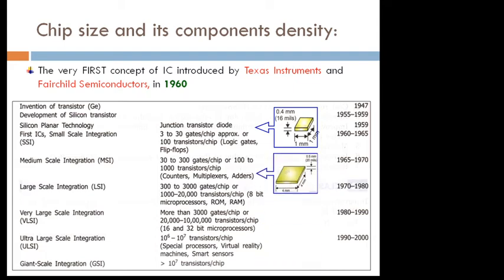अगर मैं मीडियम स्केल की बात करूं तो मीडियम स्केल इंटीग्रेशन then it would be some around 4 mm by 4 mm. So just again look at your scale, just 4 black marks from your centimeter marking, so even lesser than half centimeter by lesser than half centimeter, and again thickness is hardly 0.5 mm. And the last one is the large scale integration, just 10 mm माने 1 centimeter by 1 centimeter, and again thickness is hardly 0.5 mm.